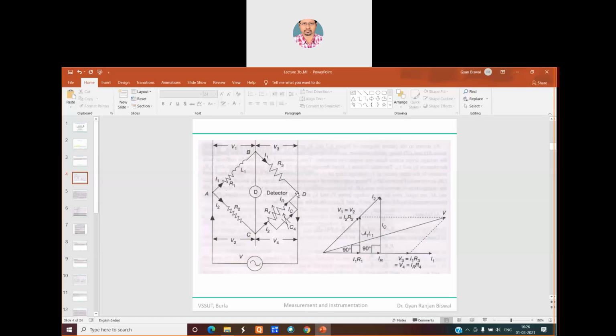Okay, so in that case effective inductance will not be equal to the sum of the individual inductances. So this can change your accuracy of the measurement. So that's why it is very difficult. Number two, manufacturing a standard inductance is the costliest and most difficult process as compared to manufacturing a standard capacitor and standard resistors.